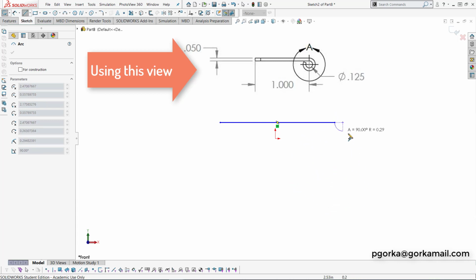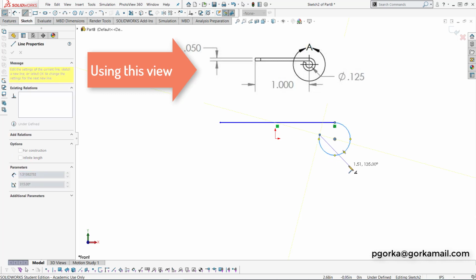It takes a little skill to figure it out, but as you go through the endpoint at different angles, the system rearranges that arc to be either tangent, bending one way or the other way. Again, that takes a little bit of practice, so be patient. But once I have the arc positioned and bending the right way, I can click to create the end of the line. I'm done for now with sketching my outline. I will hit escape on my keyboard.